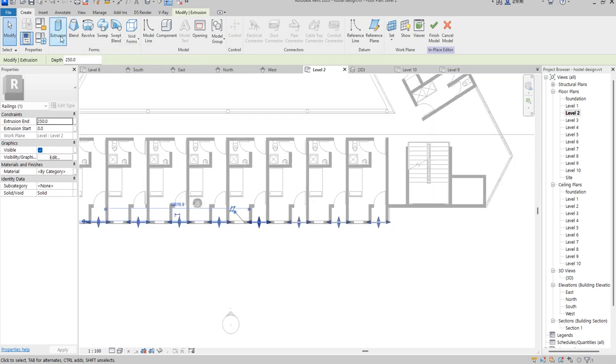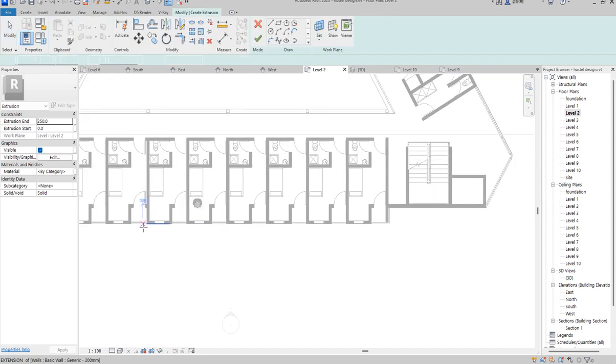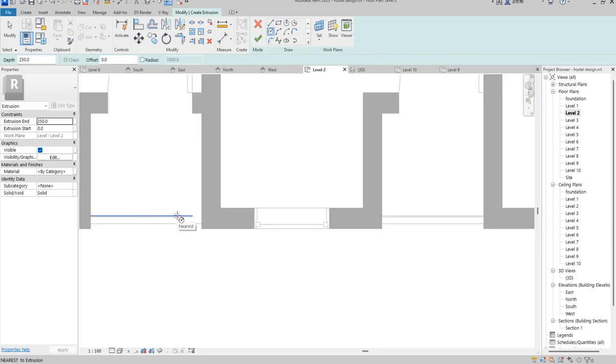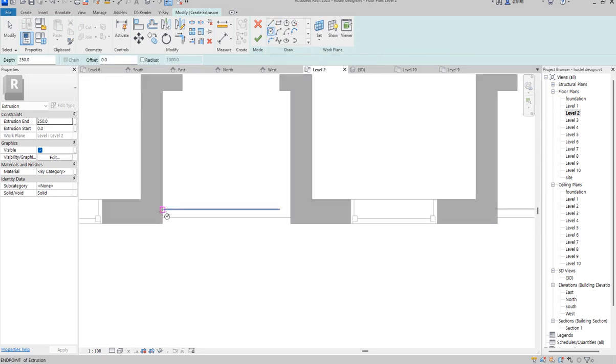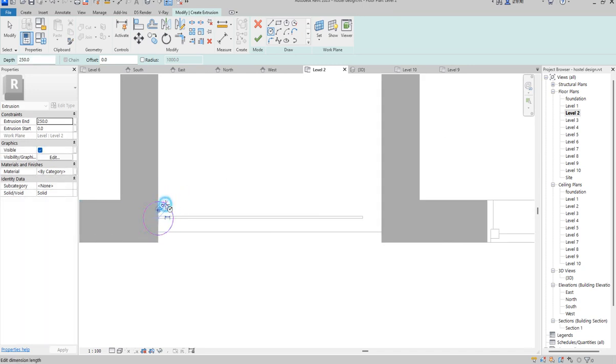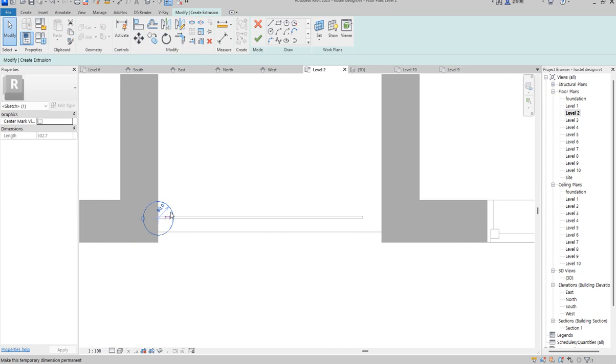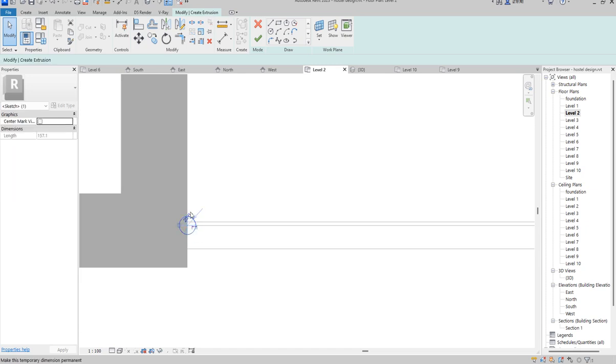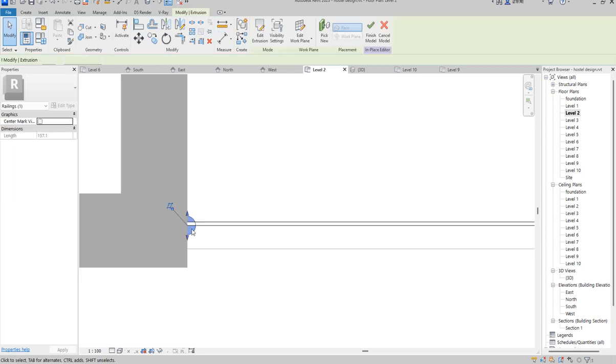So in the create that I do now, I will do extrusion. On the extrusion, I just need to draw just a circle. So you can do that on your own as well. So when you have it this way, circle, then just press escape, and say I need just a diameter of 25, so that I'm going to have the radius of 25, I'm going to have diameter of 50. So I'll just click finish.